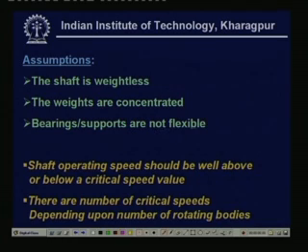That incorporates some additional deflections, and with that point, and again with the above two points, one needs a more accurate formulation than what has been displayed here. Anyway, as a first design aspect, one can use the equation given here very easily and find out the critical speed.